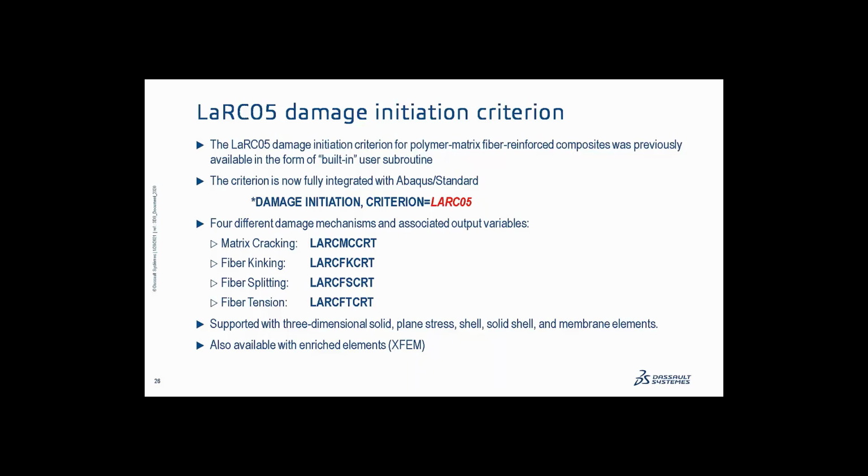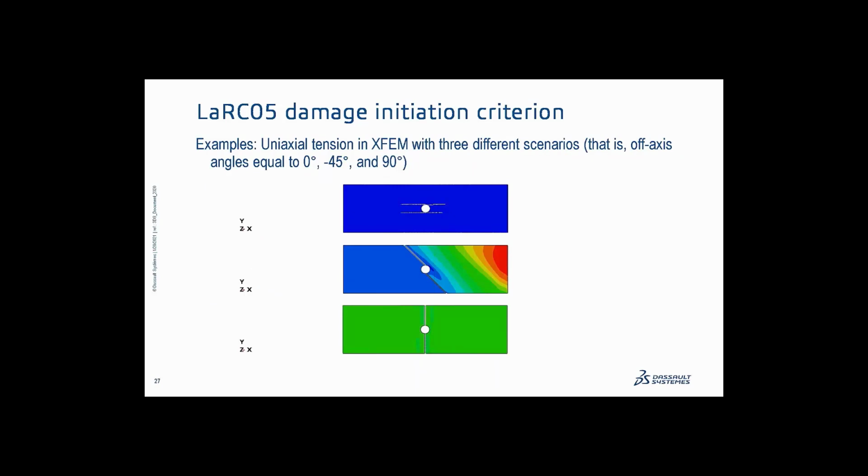It supports three-dimensional, plane stress, shell, solid elements, and so forth, and also works with the enriched regions of an XFEM simulation. So this is just a validation example that we put together using the new damage initiation criterion with an XFEM simulation. The fibers are oriented, with the principal directions having different orientations in these three examples.